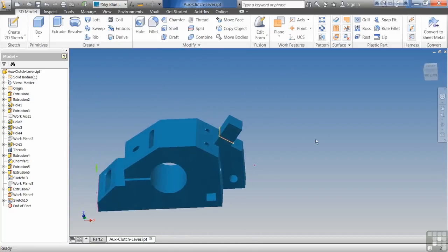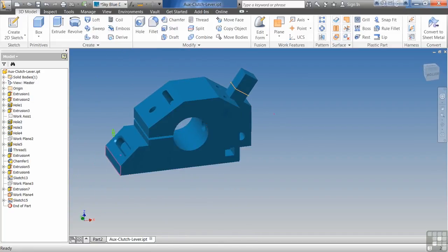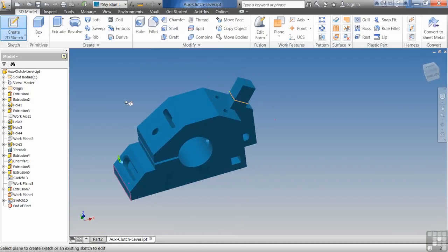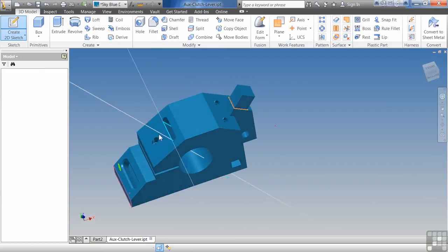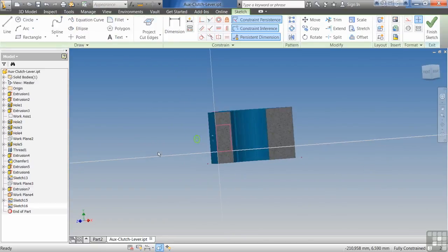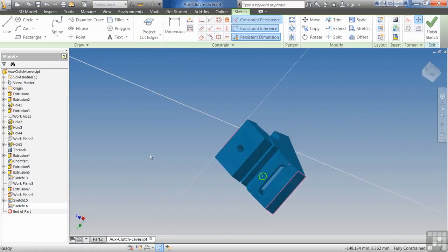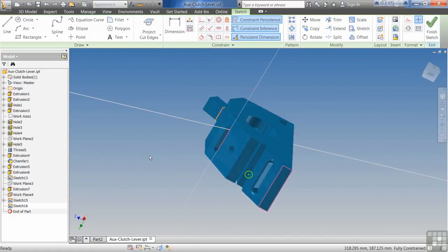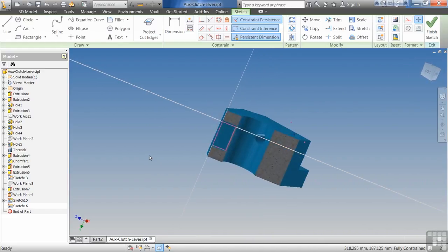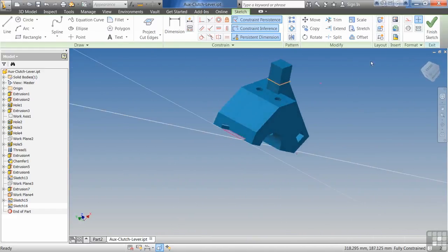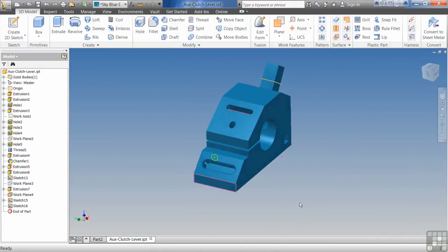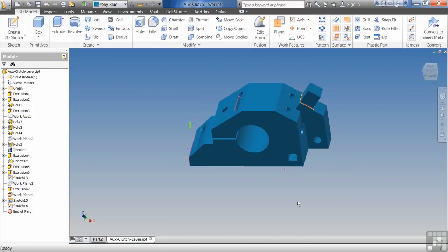But for now, remember, click on it, try it. If you're not sure, you can always undo. For example, for some reason I wanted to get into the inside of that key. Now I'm actually working inside that key. If I wanted to orientate it the other way, I hit F7 to bring back the object, hit F7 again, and it orientates me the other way. So you can see there's some very powerful sketching tools that you can play with, see what you can do, and see how well it works.